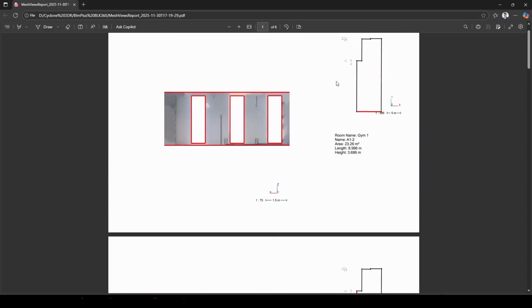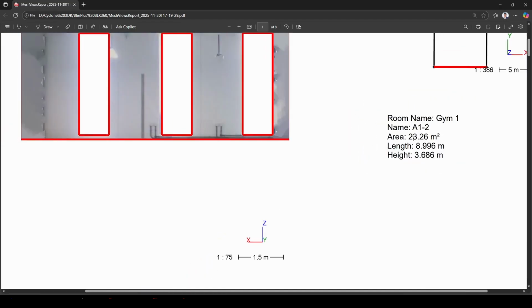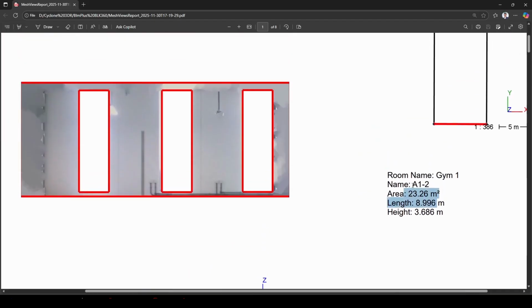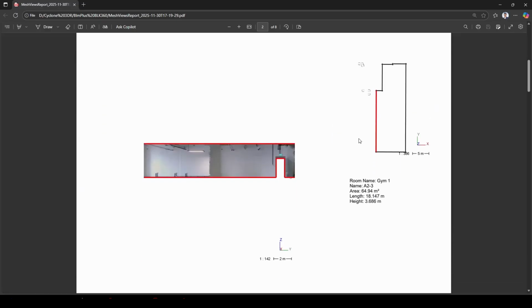And here you will have two views, the front view and top view for this wall. Script will show you the red line, the location of this wall, and here it will show you the statistic of the wall, how many square meter area, how many length and height. And that's why we extracted windows here before to get the right surface area for this wall, to exclude them.